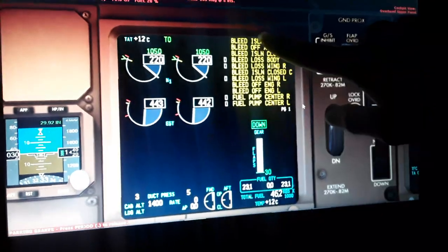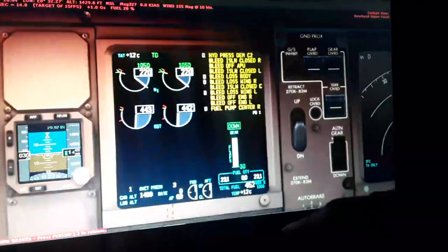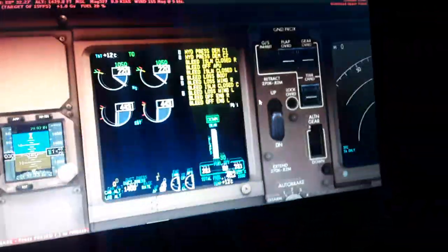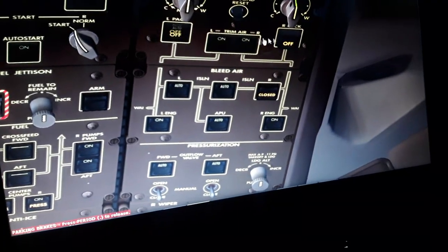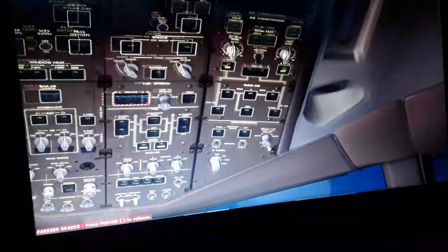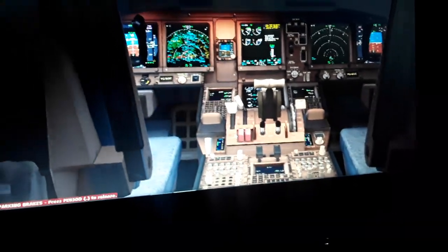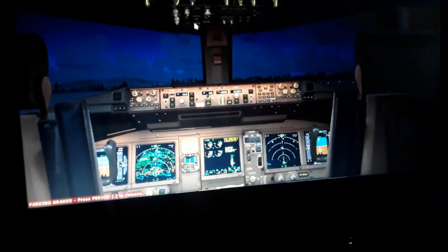We're going to lose the cabin pressurization and also some of the hydraulic pressure demands C1 and C2 here. So we turn on all the bleeds. So we're going to leave this configuration now for takeoff. Also the flaps here, 15 degrees for takeoff. So this is a nicer view of the cockpit now. I'm going to show you how to make the engine start.